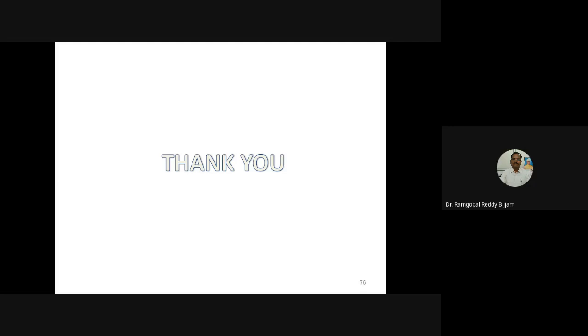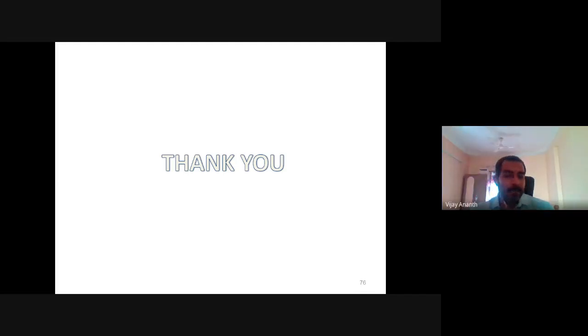So for every material, it must be heated above half of the melting temperature, but it depends on the material. Sir, it depends on the material. More and more literature works are available. I have also shown some aluminum alloys which have different temperatures. At different temperatures, we have obtained different elongations. So more and more literature is available for many materials.